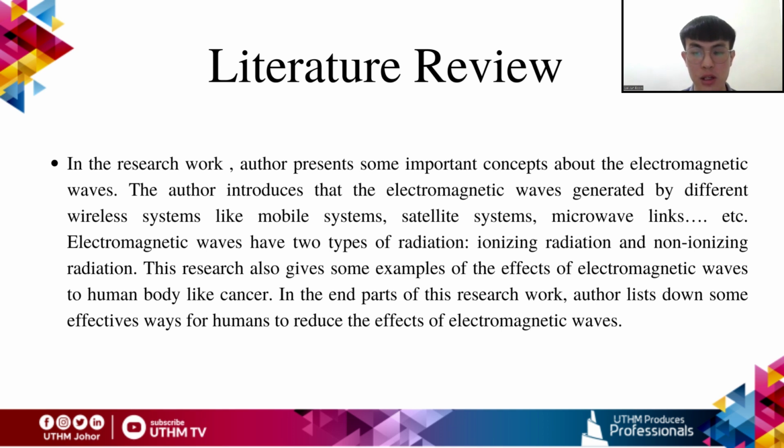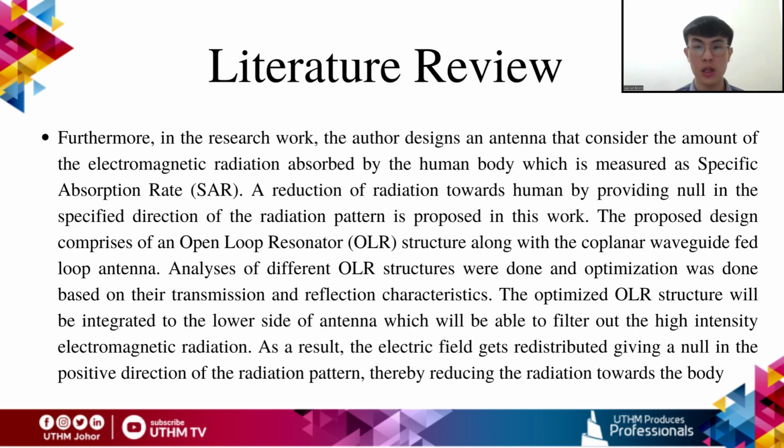In the end part of this research work, the author lists down some effective ways for humans to reduce the effect of electromagnetic wave. Furthermore, in the research work, the author designed an antenna that considers the amount of the electromagnetic radiation absorbed by the human body, which is measured as specific absorption rate. A reduction of radiation towards humans by providing a null in the specific direction of the radiation pattern is proposed in this work. The proposed design comprised an open-loop resonator structure along with the coplanar waveguide feed-loop antenna. Analysis of different OLR structures was done and optimization was done based on their transmission and reflection characteristics.